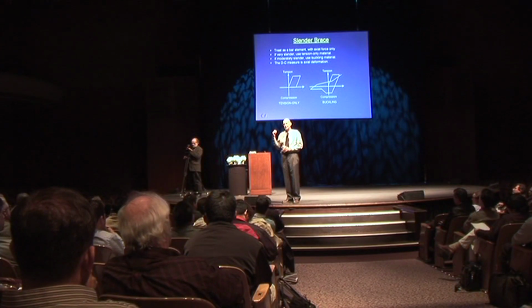In the example I gave you with the pre-Northridge connection, the flanges were actually fracturing, and then the analysis was being considered taking that into account. If you really want to push the structure until it actually collapses, I think you're asking the wrong question. I'm not sure that's an appropriate limit state.